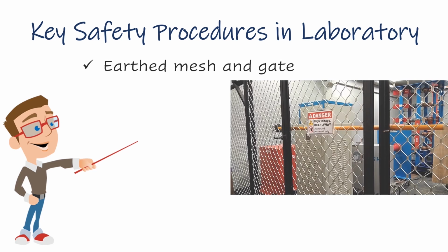Earthed mesh and gate. The testing area is separated from the rest of the ground floor area of the laboratory by an earthed mesh. So, we can assure that beyond the mesh, it is safe. Remember to stay away from the mesh. If you are touching it, the risk is still the same.